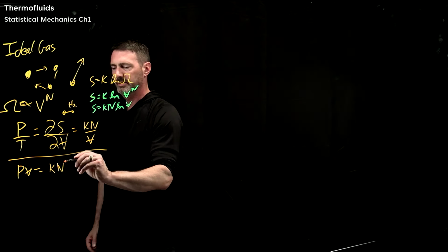You may see it as P equals rho RT, because ultimately you can combine the number of molecules and switch from the universal gas constant to the specific gas constant for the molecule. So a whole bunch of different derivations, and of course I'm going to be careful about the specific gas constant versus the universal gas constant. This is the form that we normally see for the ideal gas, okay?